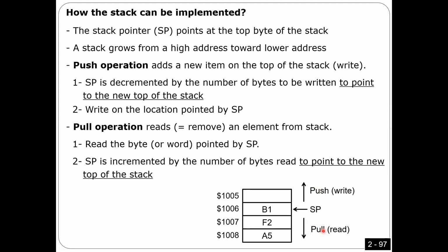Is that okay, guys? So every time I write something, the stack should grow, get bigger, right? And when it grows, the stack pointer has to move to smaller addresses. So I start from a big address, as you see here, 1008, and then when I add something, I grow in this direction. This is how they design this stack, so don't be confused. Maybe other microcontrollers design it the other way, but that's okay. It's still the same idea, same concept.